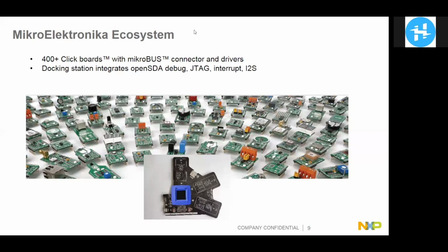Then it depends on the sensors that you will be using. We provide 8 sensing features via 6 different sensors, some motion, some environmental sensing. If you find the right sensors that you need, and maybe some that you don't need, just depopulate them from your board, reuse the schematic and the layout, and go to production with that.